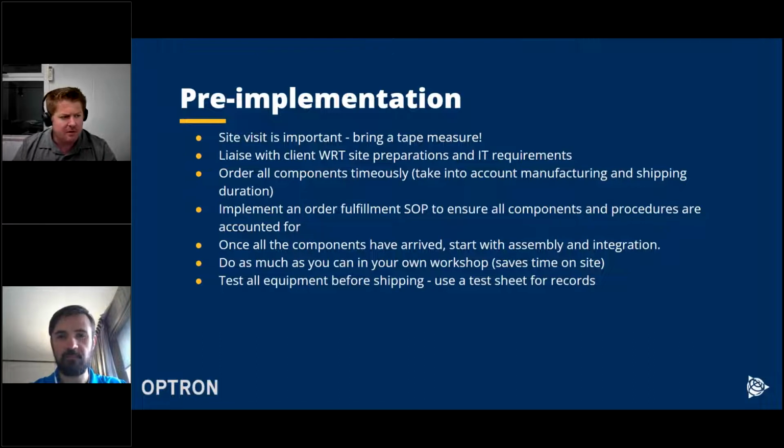And we've implemented a test sheet, so we also have a list that we run from the top. We test the voltages. We let the equipment run for at least 24 hours, what we call the burn-in, to ensure that all the electronic equipment is nice and stable and in working order.